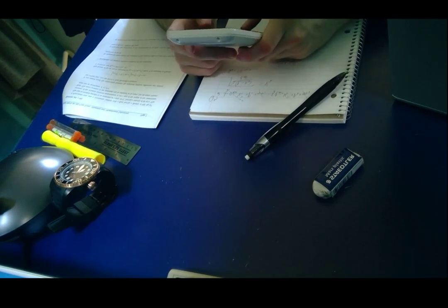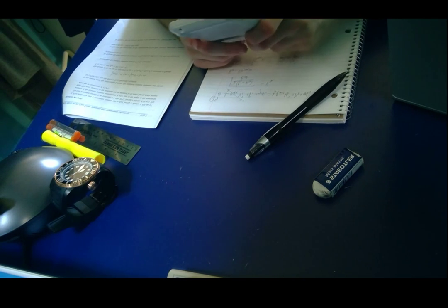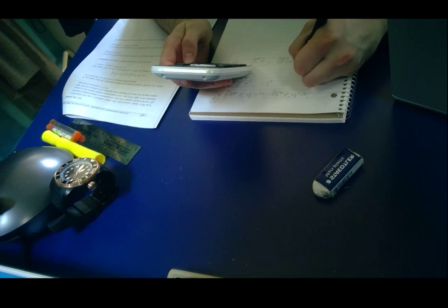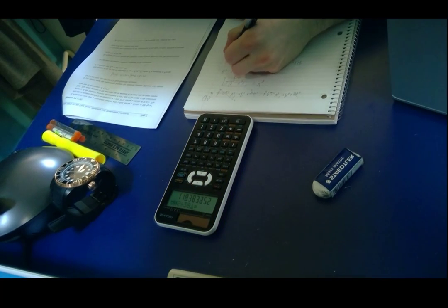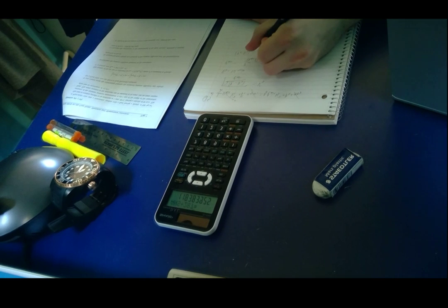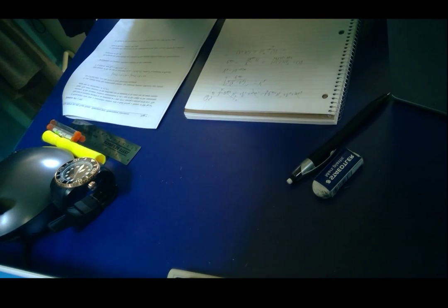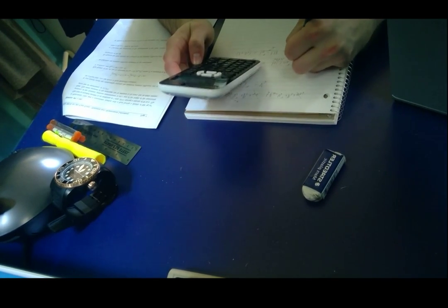So 101.3 times 10 to the 3, divided by 298.15 times 287. That's 1.18. So we have everything now, and we'll actually derive it the other way around. So P1 minus P2 is 30 squared times 1.18, all divided by 2. And that gives us 531 pascals. Because we already did everything in pascals, we'll get pascals.